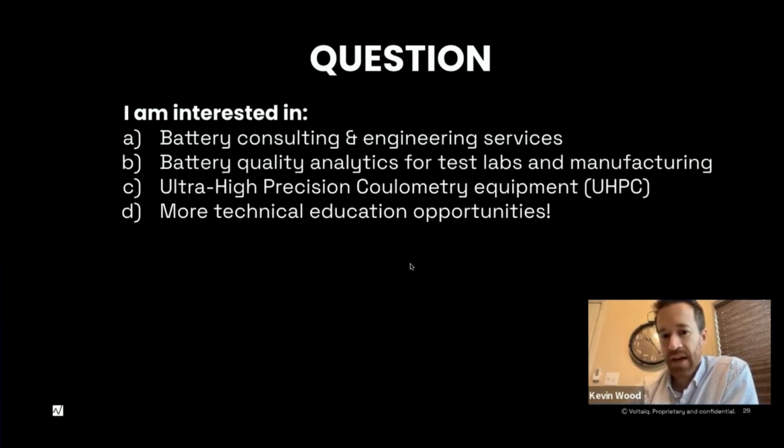A lot of times it's great to record by constant current charging steps. It's a great thing to record by a DV step. It eliminates the need for smoothing your DQDV curves. And then in potentiostatic steps and rest steps, it's great to record by some sort of DT value. You have to logically think about that in terms of what the resolution of your cycler is.